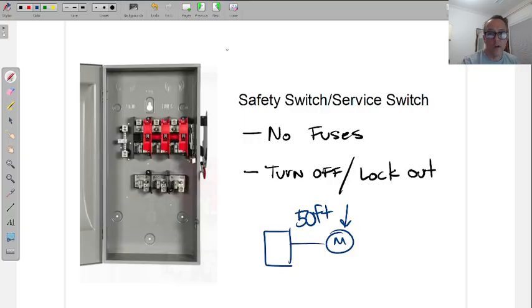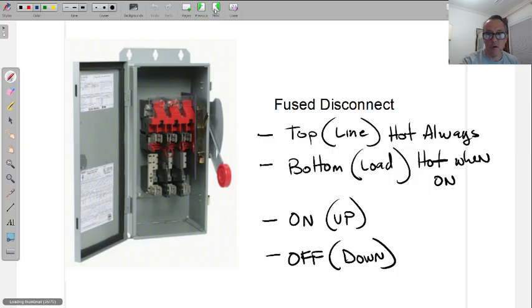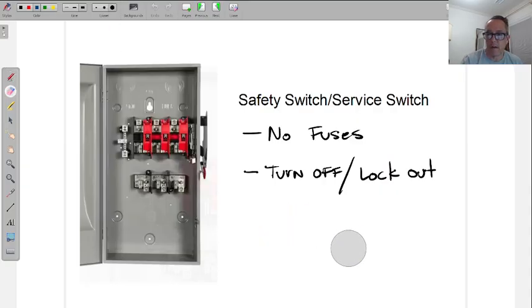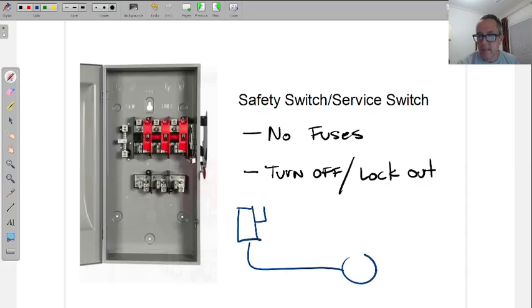So usually it's one of these, either this one or this one, doesn't matter which one, and usually it's nearby. We never put it 50 feet away from the motor, unless there's some kind of reason to do it, because there's things around it or something like that. But usually you have this disconnect and you're fairly close to the motor.